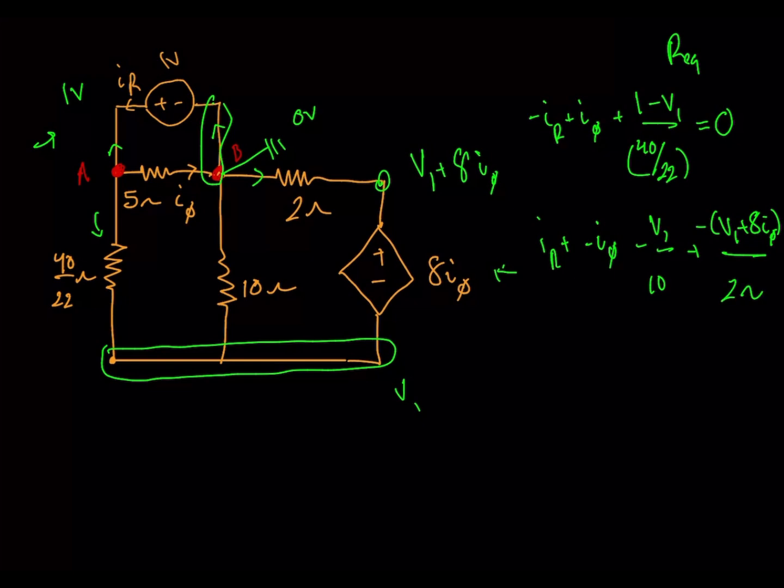We still have 3 variables, so what we can do here is we notice that I naught, since we have defined our reference node 0 volts here on this side of the resistor, and there's a voltage source here, so we know this voltage is 1 volt. We know the voltage on each of the sides, and we know the resistance, so we actually know I naught. So if we look at I naught, that'll actually be equal to 1 minus 0 volts, which is 1, divided by the resistance, which is 5. So that'll be 0.2 amps.